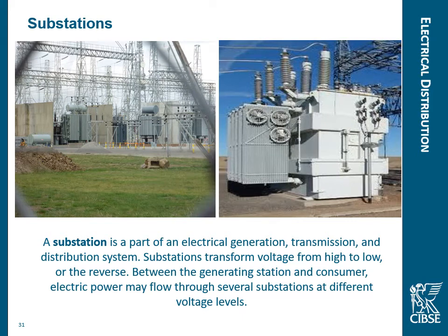We've probably all seen these as we drive around the country, or perhaps see them in city centres. Not overcommon in city centres, quite often in more rural areas, just outside city centres. And these are substations. These actually take the electricity in at quite high voltage and transform it down. And we can see on the transformer here, we've got fans and radiators, and this is to disperse away the excess heat.